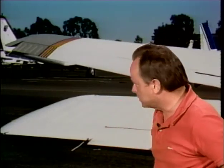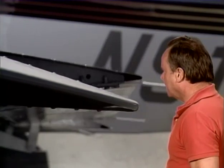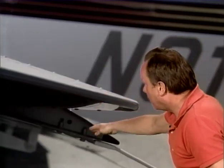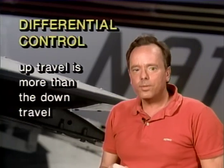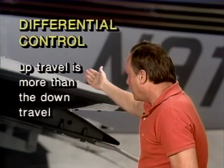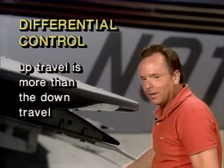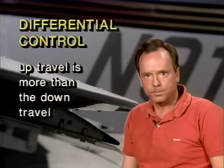All right, now sometimes you have differential controls on ailerons. Let's you and I take a look at differential controls on ailerons. Here's the up travel. It's a great deal of travel, and less travel on the down part of the aileron. That's what they call differential control on an aileron system, and it means the up travel is more than the down travel. And what that does is that adverse yaw is eliminated or reduced by having it done that way. Not eliminated, but it is reduced.